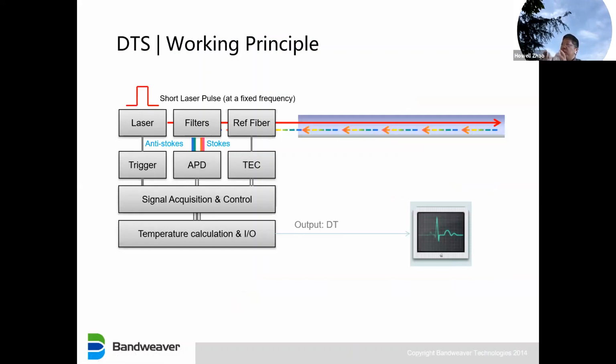Normally one temperature sensor can only monitor one point, but this sensor we call a distributed temperature sensor (DTS). It means we can get quite a lot of data, every 1 meter we get one data point. So if the application needs to monitor more than one point of temperature data, it will be more cost effective. And on another side, with any kind of high tech, the cost will drop dramatically because of the volume.